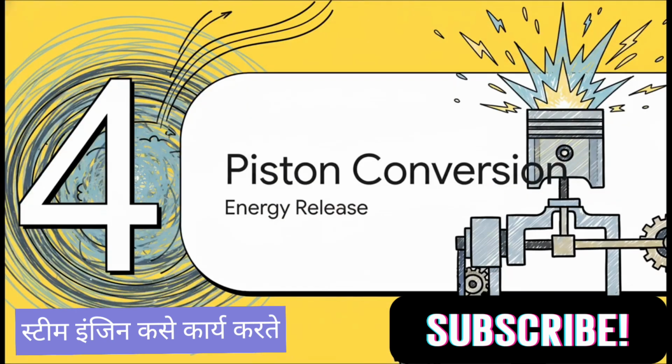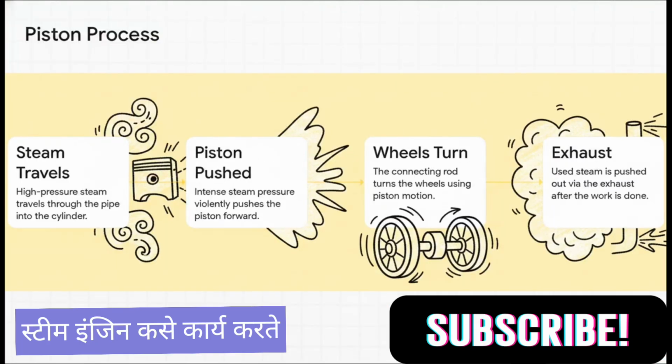Section 4. Piston energy conversion. Now for the payoff. Step 1, that high-pressure steam travels violently through the pipe and straight into the cylinder. Step 2, because the steam is under such intense pressure, it pushes the piston forward with incredible force. Boom! Step 3, as the piston shoots forward, the connecting rod moves right along with it, transferring that straight-line movement into the turning of the wheels. Step 4, finally, after the work is done, the used steam gets pushed out via the exhaust, clearing the cylinder for the next cycle. Push, pull, push, pull. And this brilliantly illustrates how these final steps convert that stored pressure into actual turning mechanical work.